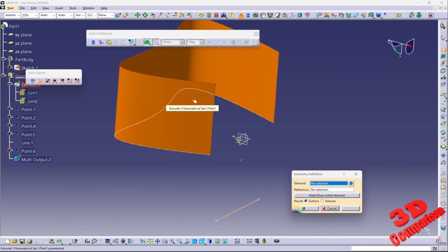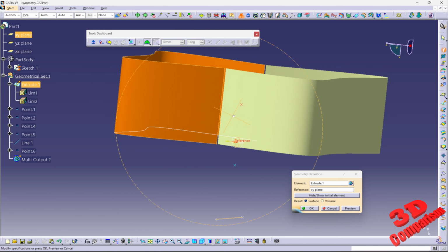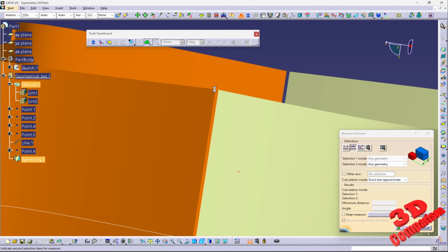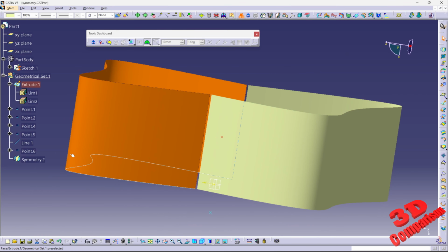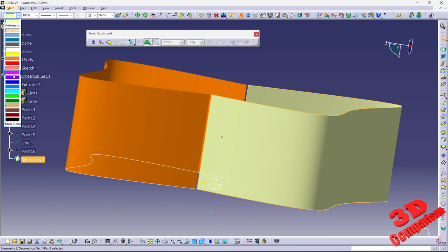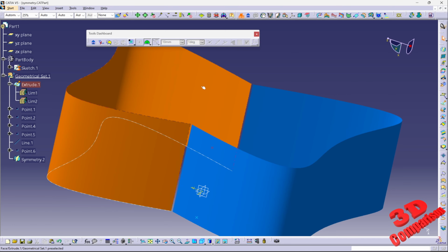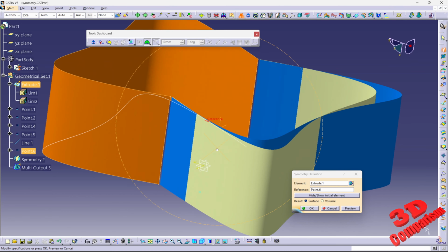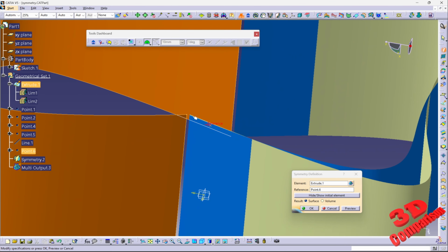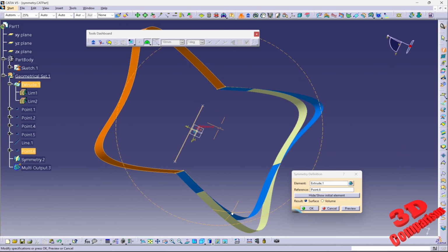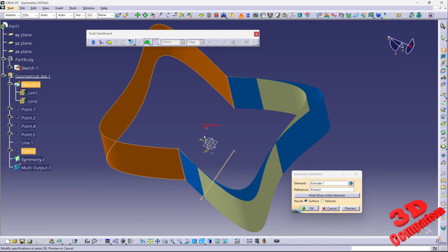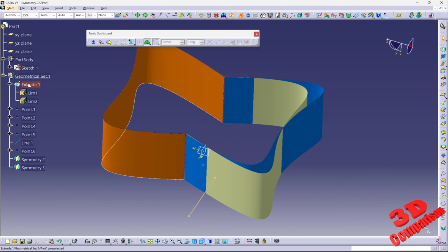If, for example, I do the mirror regarding this plane, we're going to see that this offset distance will remain just like the one with the point. So 3.28 millimeters. Let me just change the color for this, for example, to black. And I will recreate this Symmetry regarding the point. And we see that offset is set like that, but in this case, the mirroring of that shape will be turned around, as we can see from the point, because the point will give this a different normal, and that will give it a different axis over here.